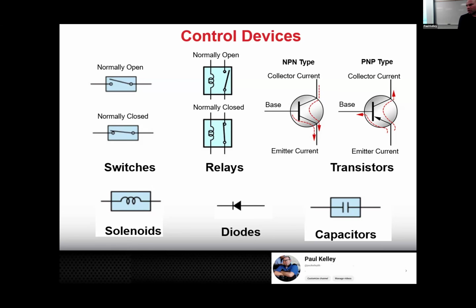But on the right side, the high current, that's going to be like a 15 amp wire, like a 12 gauge wire or something. Right, we can't be running huge wires through the ECM. The ECM's made for little low current electronic stuff. Cool, so the normally open relay is by far the most common. This relay will sit there and not power the thing, the fuel pump, until it gets 12 volts and ground on the control side, and then it'll power the fuel pump. That's normal. There's some exceptions though.